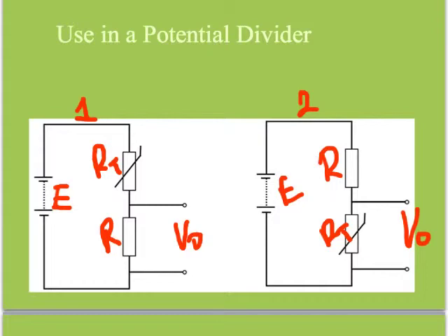But essentially, if the temperature is going to increase, then the resistance of the thermistor will decrease, and that means the voltage output would increase. If that was 10 volts there, and we shared it amongst these two resistors, and this resistor stays the same, then the ratio of the two resistors will depend on how this one changes. If this one goes down in its resistance, it's going to have a smaller ratio.